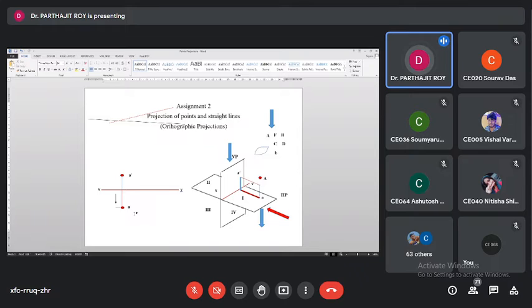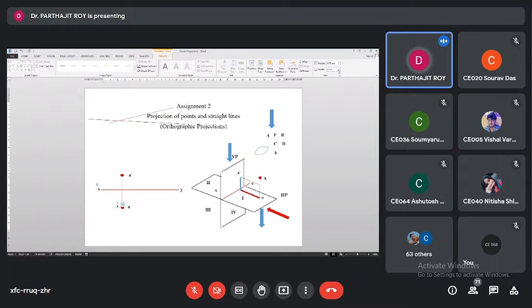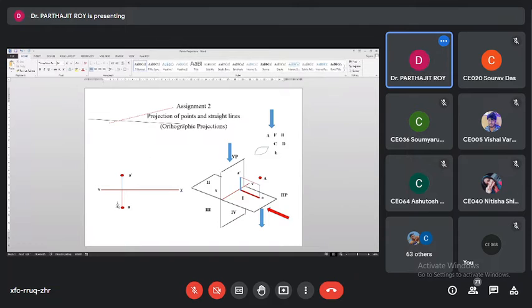So after a gap of 1 millimeter from the point A, you draw a horizontal line of length 8 millimeter, and then you draw the arrowheads. Arrowhead will be filled up. Okay. Arrowheads will be put on both the sides, both the directions, upward direction and downward direction.